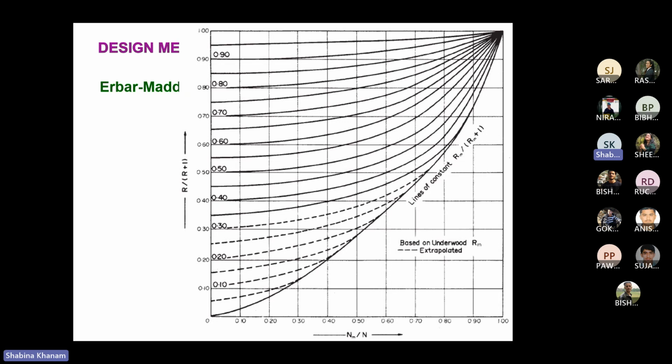And you know already, as we move to increase the total reflux, the number of trays will keep on decreasing. Similarly, if I'm having the least reflux ratio, the minimum reflux ratio, the number of trays would be maximum. So Nm we need to identify, and Rm we need to identify.